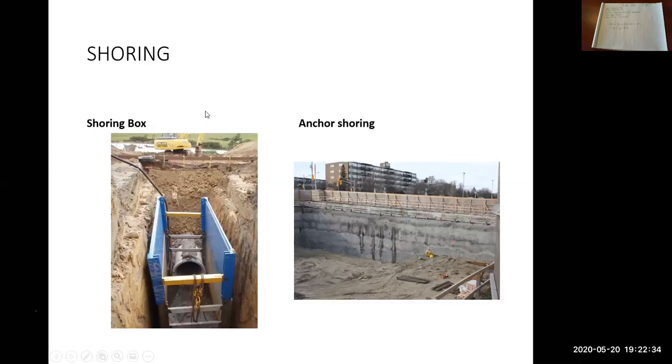So that was sloping, so into shoring here. So we've seen the trench cage before, so the utility pipe is sticking out of it. So the cage is there so that the workers can go inside the cage and do their work in there safely. So if the trench walls were to fail, the trench cage would hold the dirt out so the workers wouldn't be buried.